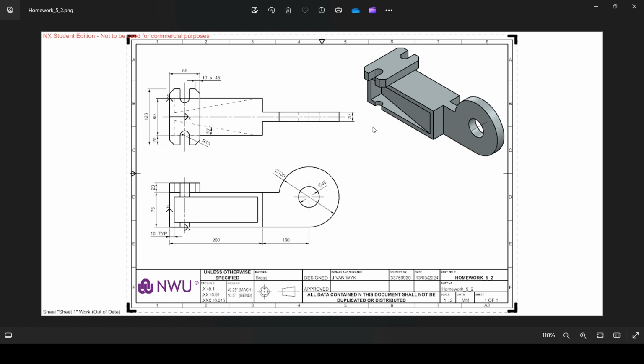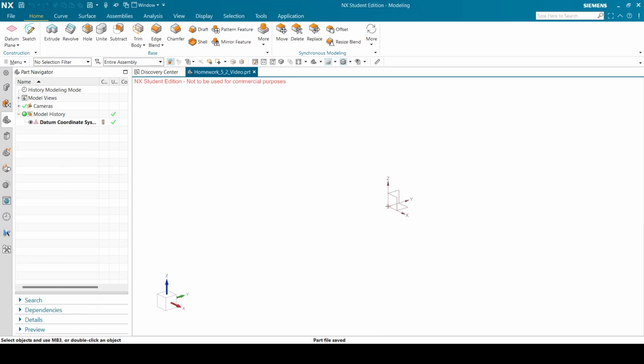So that's going to be my strategy. I'm going to first create the side profile with three extrudes, then add the cutouts, add the chamfers, and then add the draft. That also hints at what I'm going to use: I'm going to use draft for this. Many of you had different ways of doing it. I'll chat about that a bit later. Okay, so let's get started.